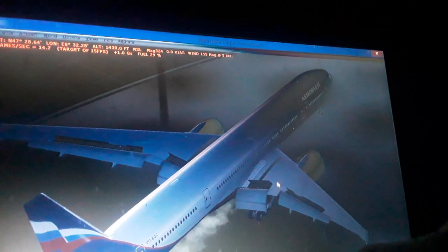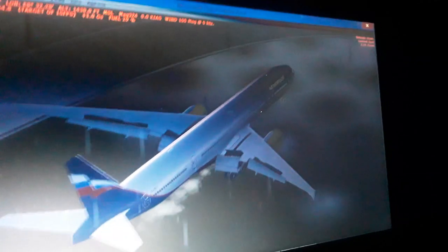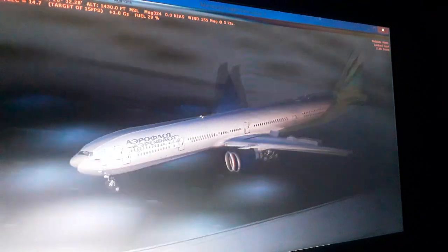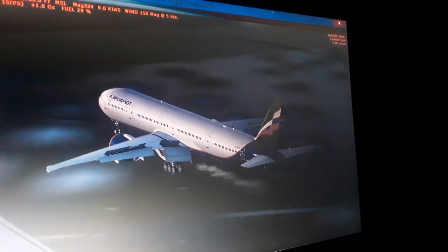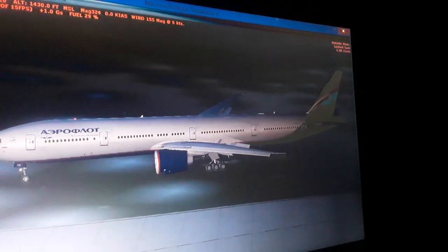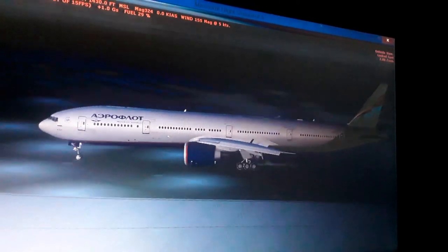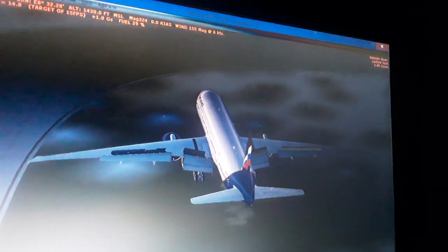This axis, this vector, using Newton's physics. So you can shift the center of gravity of the airplane forward or aft of this position by moving fuel and passengers around the airplane, increasing or decreasing the weight. So you can make the airplane more or less controllable in flight.